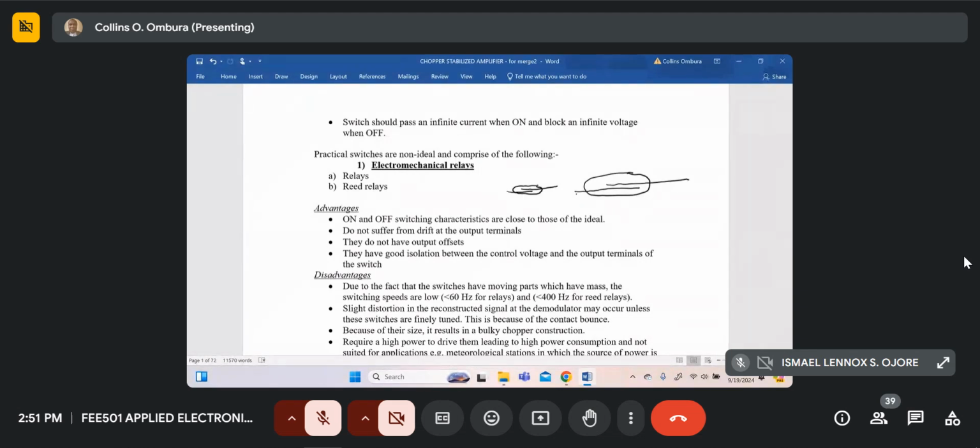So this is normally in a glass bulb, which is vacated. Then there's a winding around it. So these contacts inside the glass are magnetic. So when you put a magnetic field, the two will attract each other and close. But the size is very small. They are normally around, if you've seen 1/8 watt resistors, they're that size, quite small. But since the moving parts inertia, the weight is very small, you can open and close this switch very fast.